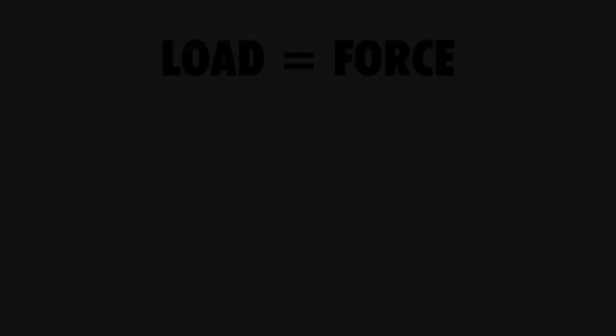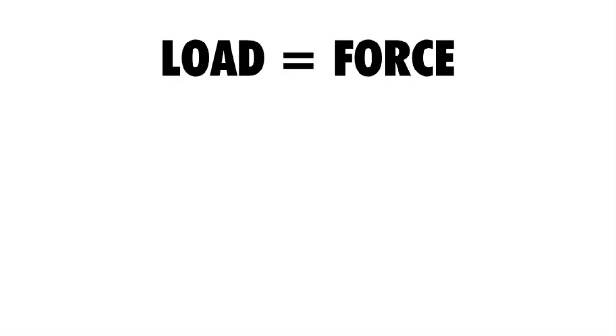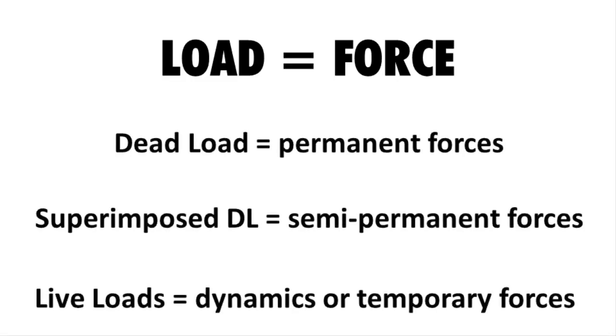In summary, a load on a structure is a force acting on that structure. There are different types of loads. Dead loads are forces that include the self-weight of the members or parts of the structure that are permanently fixed. Superimposed dead loads are semi-permanent forces, and live loads are dynamic or temporary forces. A point load is a load that is applied at a single point or over a small surface area.